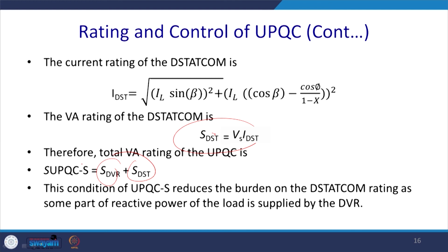This computation in UPQC reduces the burden of the D-STATCOM rating, as some portion of the reactive power and active power of the load is also supplied by the DVR.